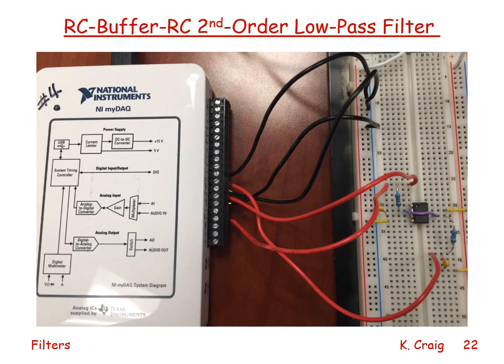Now, I put a buffer in between the two RC low-pass filters. So here I have one RC low-pass filter. Here's the other RC low-pass filter. And I have my unity gain buffer op amp. The unity gain buffer op amp ideally has infinite input impedance, zero output impedance, and will prevent the downstream RC circuit from loading the upstream RC circuit. I want to determine the Bode plot, the frequency response plot, and I make the connections just as I did previously.